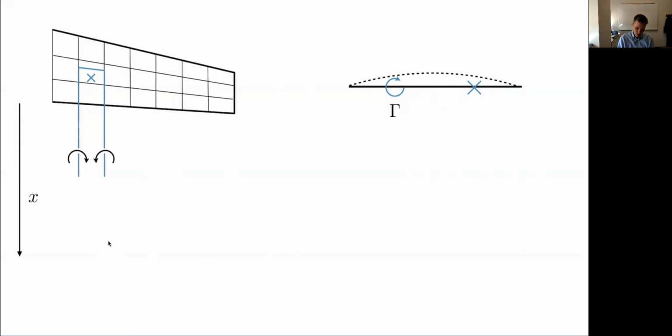Previously with thin airfoil theory, I'm not sure if I derived this on the video, but I certainly do in the book. We had looked at a case where we had an airfoil, actually I started drawing here, with parabolic camber. And we tried to figure out where to place a lumped vortex. So if we took all the vorticity on that airfoil and we just lumped it all into one spot as a point vortex, where should that go?